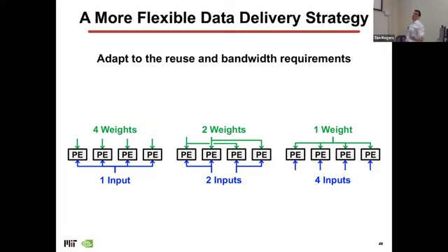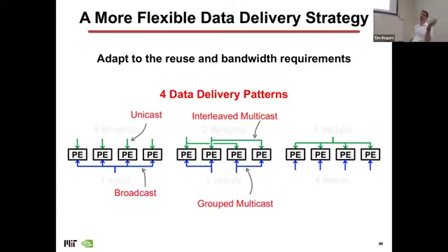Right. So why would I do this? Why do I want this high-level estimate? I want this high-level estimate because I want to decide how to build the DNN accelerator. This is before the thing is built, right? Like an architect, I want to figure out what I should do, so I could potentially change things like the configurations of the networks. For example, I could configure the PEs such that I have a unicast to every PE for the weight, and then a broadcast to every PE for the inputs, right? Or I can have these interleaved multicasts. I can play games with the way I've connected these PEs, and I can account for that in my spreadsheet model to affect the bandwidth and tell me what the performance is going to be